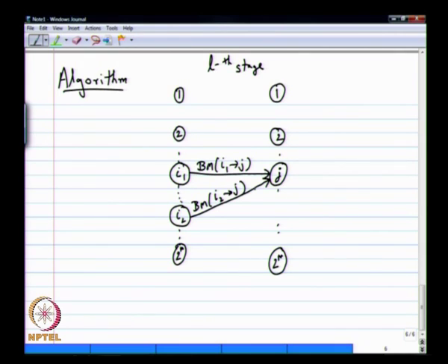Now, in my algorithm up to the L minus 1th stage I have already done something. Which means for state I1 I will be remembering one particular path, and that path will have a partial path metric up to that point I1. That is called the state metric for this state I1. So let me write that down. You have the all 0 state. Well, I am starting from 1 here, right. So that is the problem. Let us say 1 the 0th state.